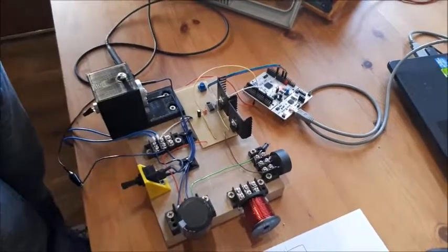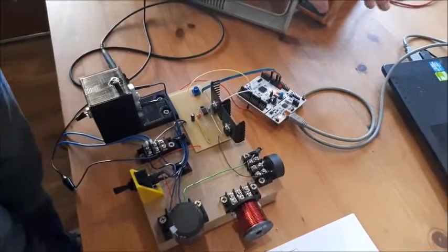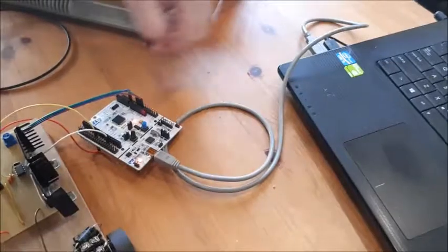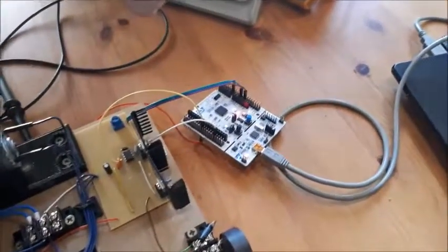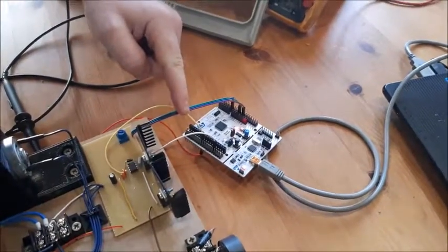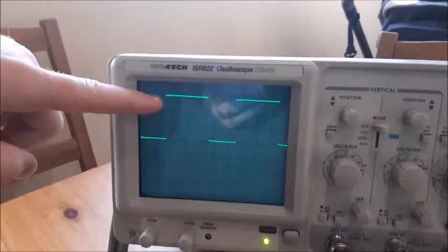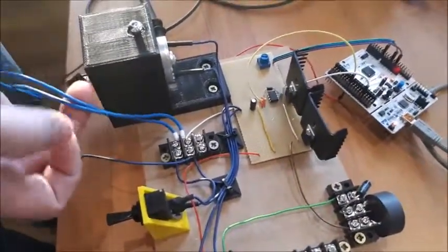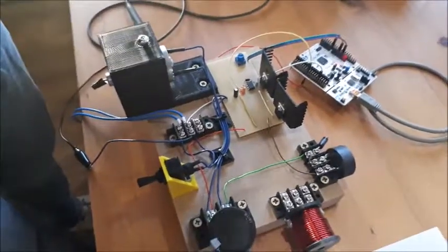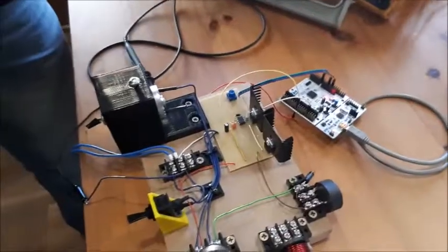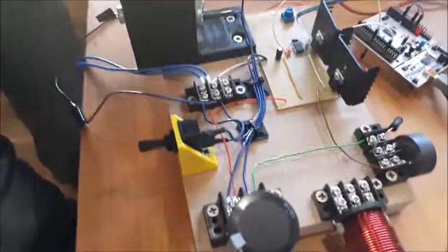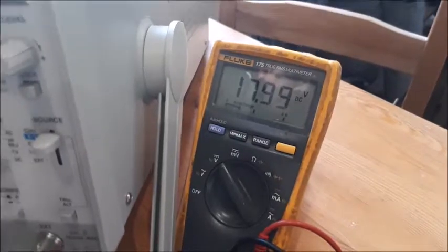So just to explain a little bit about the voltages that we've got going on within the circuit, we are powering the STM board via the USB from the laptop. This takes a 5 volt input but gives us a 3 volt output on our pulse width modulation. This can be seen on the oscilloscope. So the divisions we have here are 1 volt per division, so 1, 2, 3 for our 3 volts. We then have an external power supply connected in. This is giving us 18 volts. This can be seen by using the multimeter and connecting it across the connection points. So 1 point here, 1 point there, and you can see that we are reading 17.99 volts.